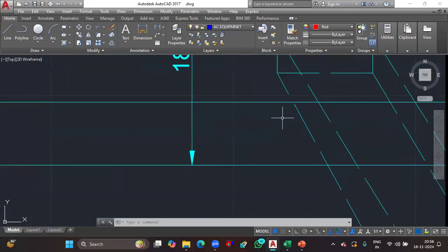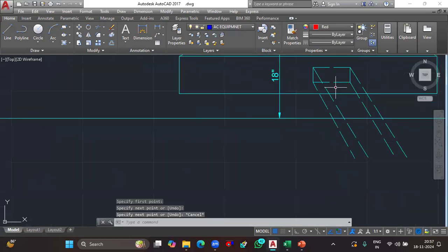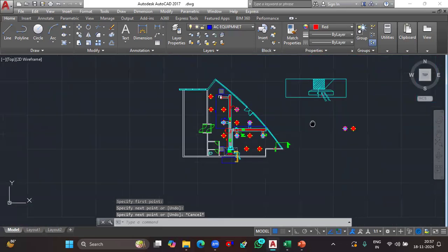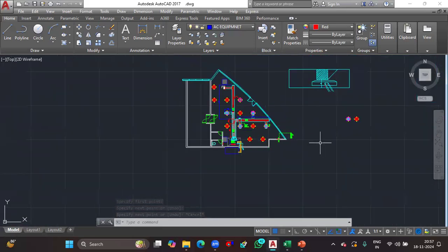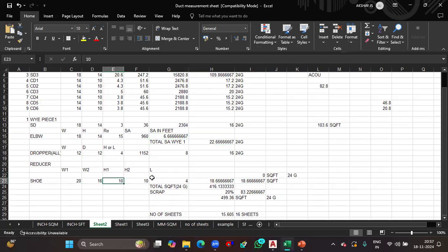That means now you will be having 2-inch clearance on this side, and 2-inch clearance on this side. Am I right? 2 inches clearance on this side and the remaining 2 inches on this side. So total it should be 2 plus 2, 4 inches. So the total dropper length should be around 4 inches, around 0.5 feet. Okay, that's it. Is it clear? That's how we calculate the value. So here they've considered the length to be 4 inches. You can see this now.